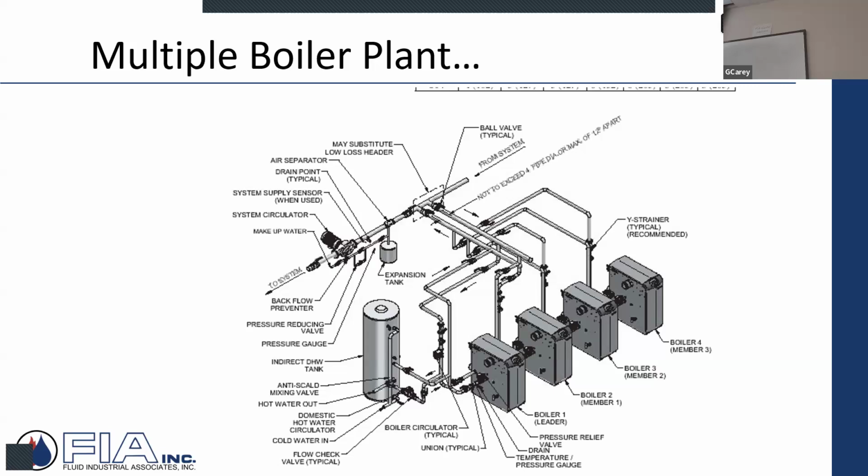It could be a hospital. It could be anything. But distribution pumping, again a simple little pump right here, but you're probably talking 50, 100 horsepower base mounted pumps, 2 or 3 of them. And then I've got these boiler pumps supporting the 400 gallons a minute if I'm doing a 20-degree delta T, so 1,600 gallons. A lot going on here.